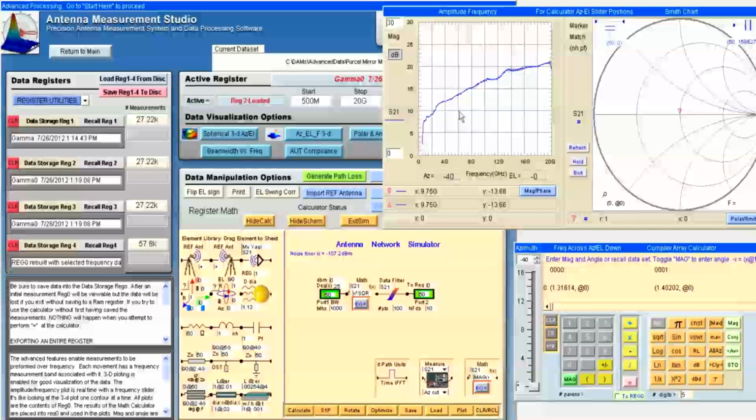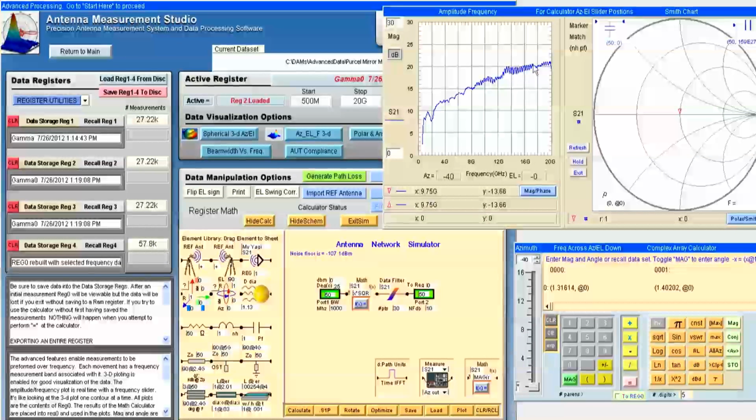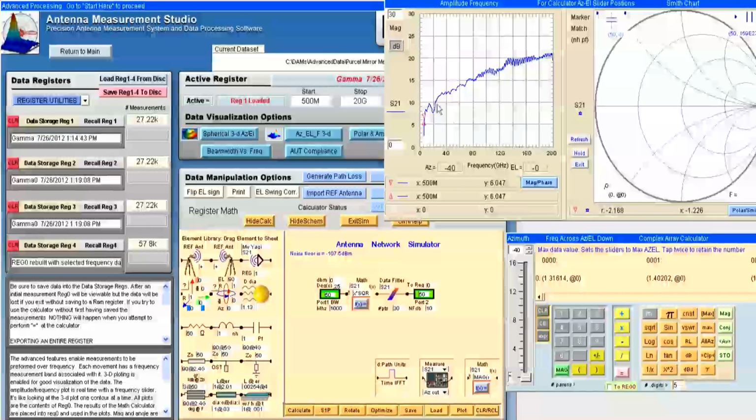What we can see is that we've oversmoothed the data. Some of the known variations are now smooth. Choosing the proper number of points requires some user experience. I'm going to go ahead and use 30 points. Here we can see the horn's natural variations along with the small degree of error. Now we have a fairly accurate representation of the horn.